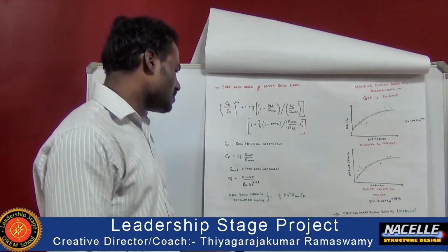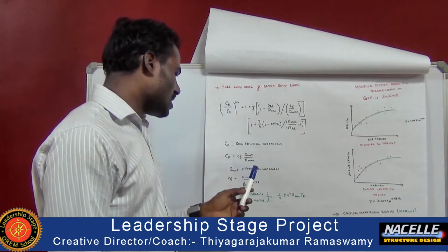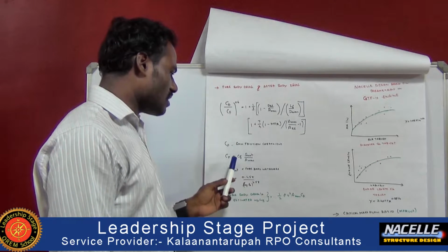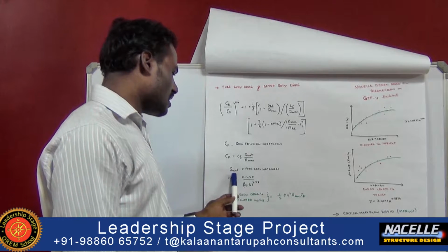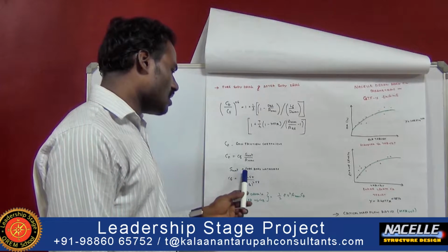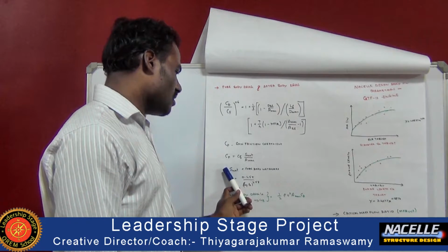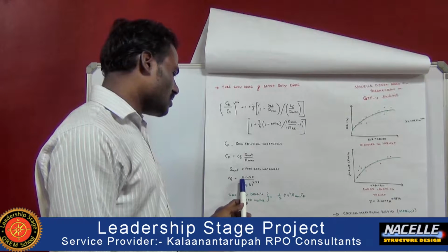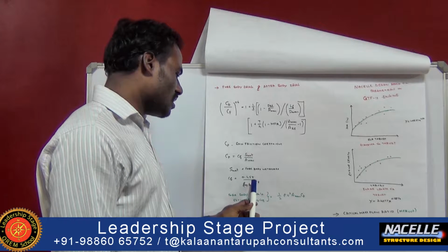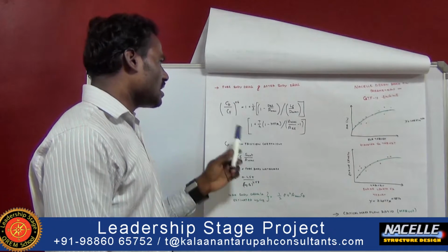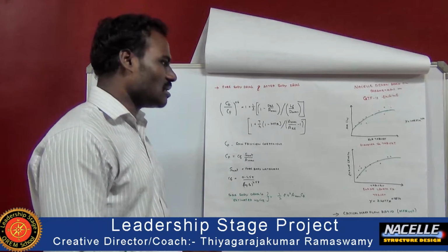Then we are just finding out what the skin friction coefficient is. Here, the skin friction coefficient is calculated using CF times S weight divided by A max, where S weight is equal to the forebody wetted area, whereas CF is calculated using 0.455 divided by log Re to the power 2.58. The entire forebody drag as well as the coefficient of discharge is calculated with respect to the Reynolds number.